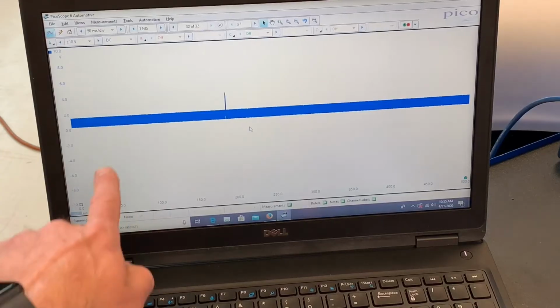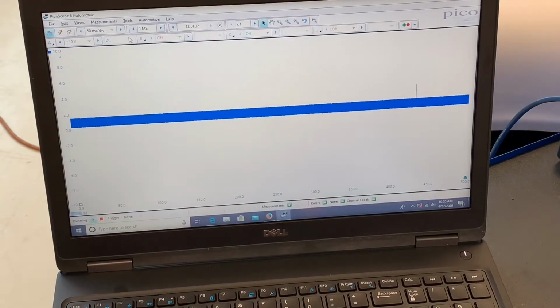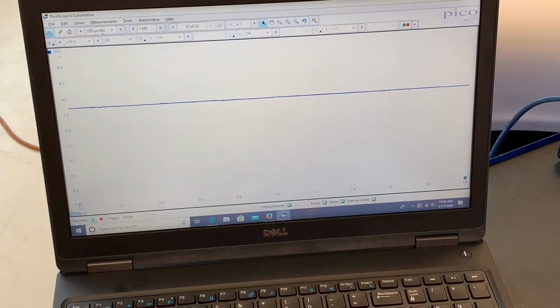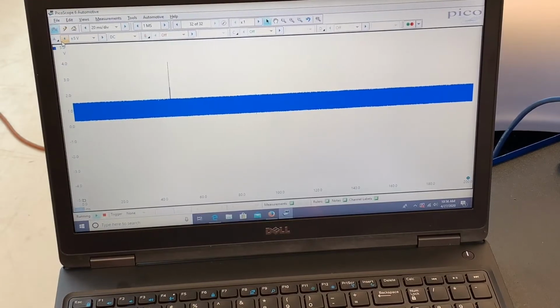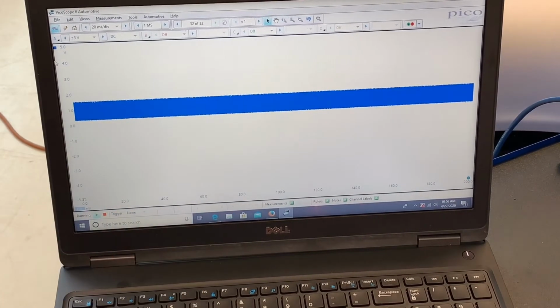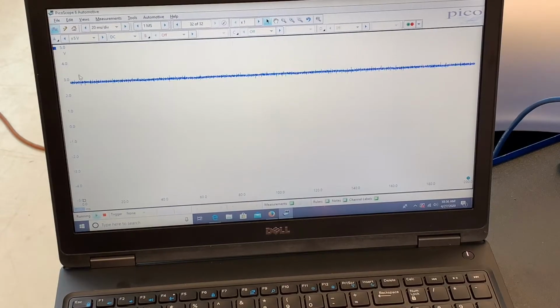Right, so right there you can see this is activity from the scanner trying to make contact with the TCM. And if you notice, I have to go way down here to see what was going on with that. The transmission rate was quite high on those. All right, so here's my scan tool. I switched modules, trying to communicate here with the ABS module. And so you can see a lot of activity that's taken place.